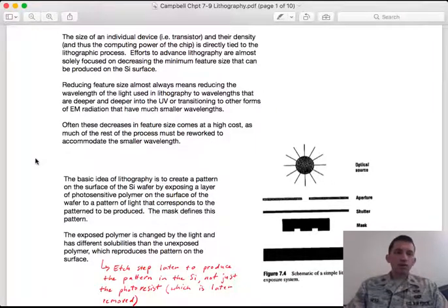And so we talked about on the very first day Moore's Law, which you are probably all familiar with. It describes the exponential growth, or the exponential reduction in individual feature size, and thus the growth of density: you get a doubling every 18 months or every 2 years or whatever of the density. Achieving those gains has been almost solely the result of advancements in photolithography, right? As you get better lithography, you can decrease the minimum feature size, pack more of them in there, and have a faster chip.